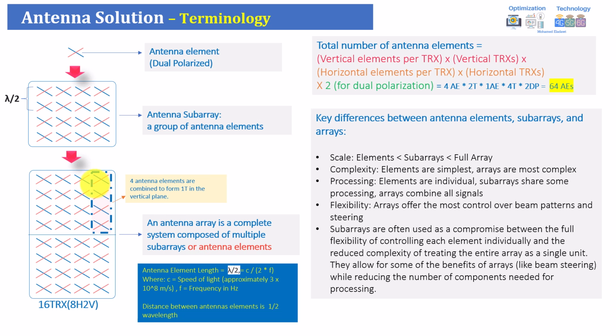But what if, instead of this, you remove that and keep only one clock for all of it? The more antenna elements for one transmission, the higher the gain, for example in the horizontal plane or even the vertical plane. We'll explain this in the future with more examples, just to be clear. But for example, assuming that in the vertical plane you are using 4 antenna elements, you will have control over your vertical plane. But if you increase the number of antenna elements, instead of 4 you make it 6 or 8, this means your beamforming, or even the antenna directivity in the vertical plane, will be much higher.